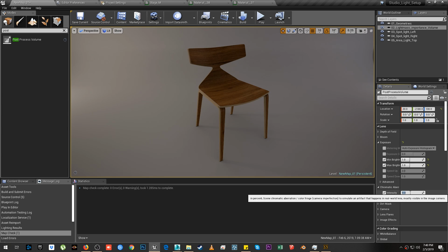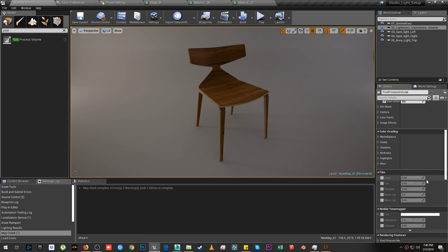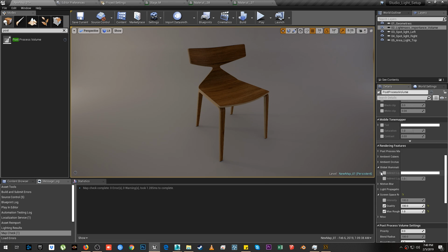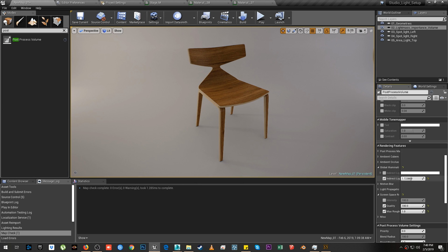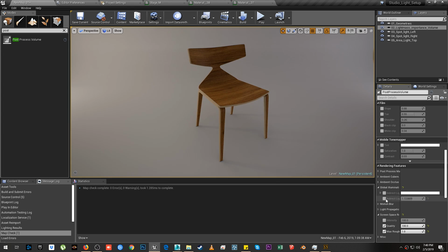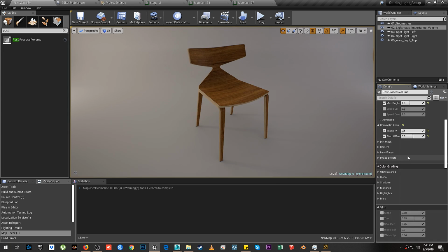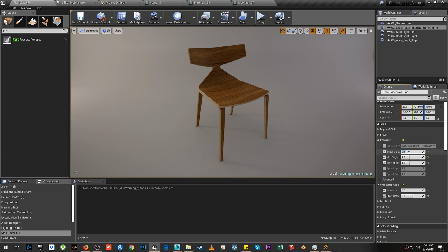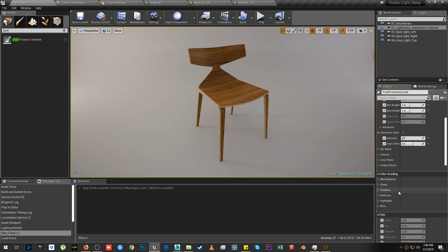We'll give chromatic aberration 0.5, 0.5, 0.5 and 0.5, and then we'll go inside here in global illumination, and then we will increase it a bit, and then we will increase the exposure to maybe 0.25 or maybe 0.5, and if you see what's the effect, go ahead and make it 1, and that is better.